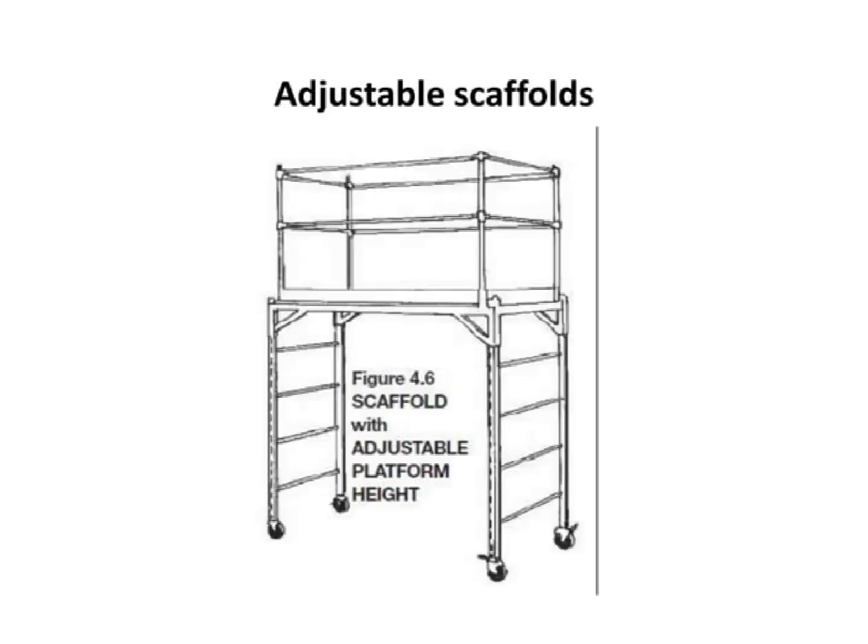Adjustable scaffolds are a key component to ensure safe access to work areas at higher altitudes. Their platform height can be adjusted and guardrails can be installed to secure the user. Proper training in the use of adjustable scaffolds and adherence to safety measures is essential.